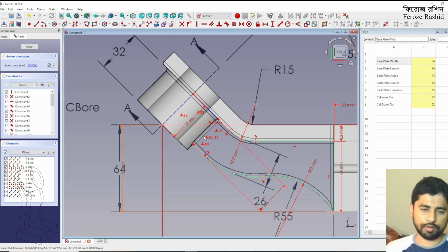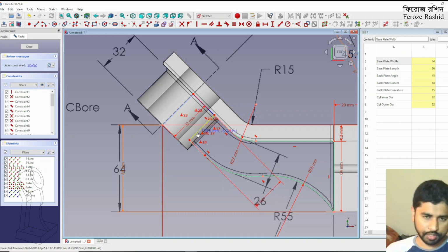But think about it, if I extrude it on both sides, because this point is the farthest point of the cylinder, there will be a gap between these two objects. I want to make some overlap. I want to keep it right there. So this line would be half the diameter of the outside, half the diameter of 52 minus some overlap.